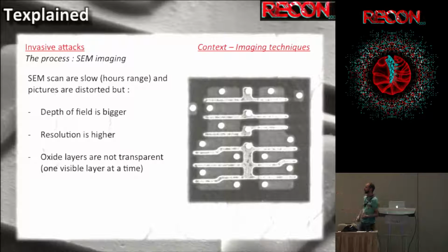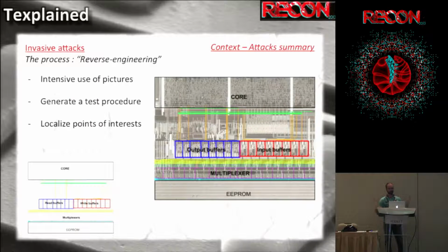I see the active areas, I see the polysilicon gates, I see the contacts, the tungsten plugs. I see everything, so I feel all right because I have a lot of information on my picture and I don't miss one. So once you did the right choice and you scan your chip this way, you can just put pictures together and you can start to study things.